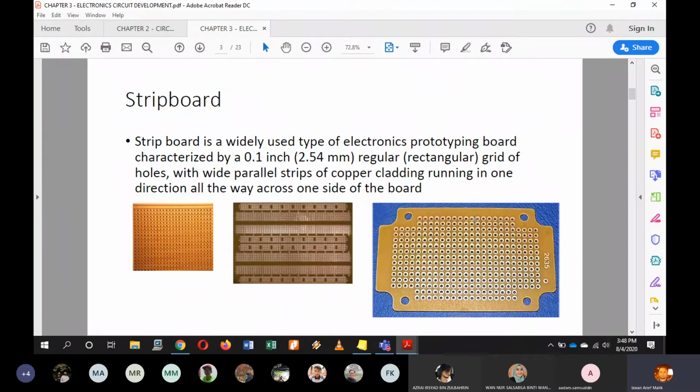Okay, prototyping is pre-construction. We want to try doing the soldering, measure all your components, whether the leads are long enough, how long the jumpers you need, and how large the area on your board you'll be needing for designing later on. So you can use this.